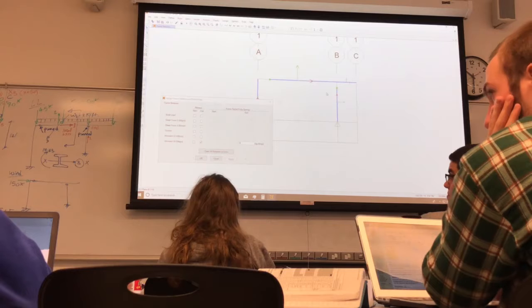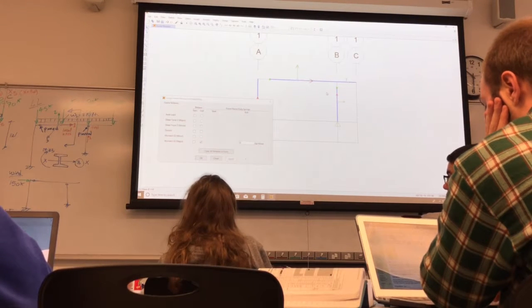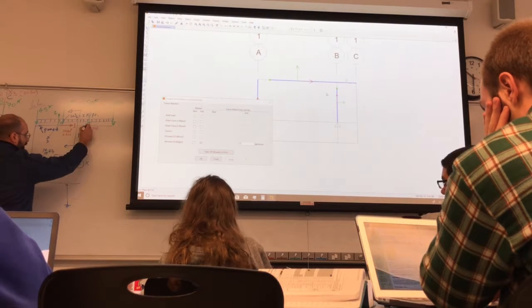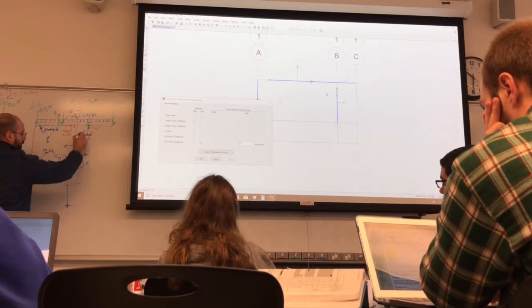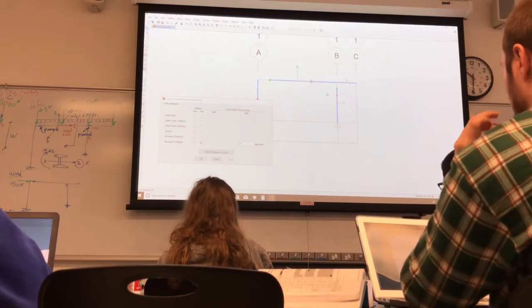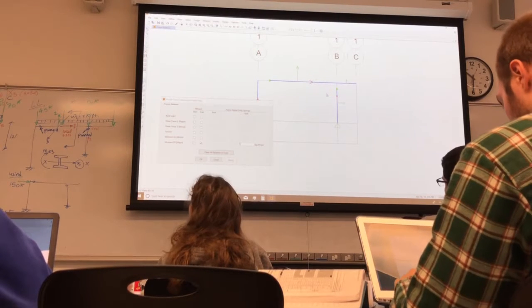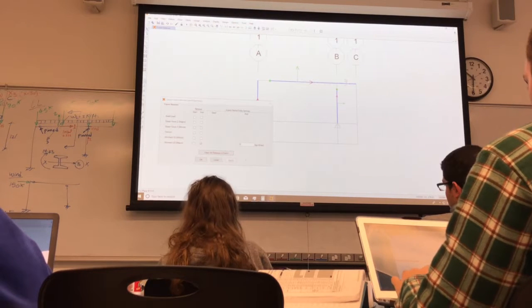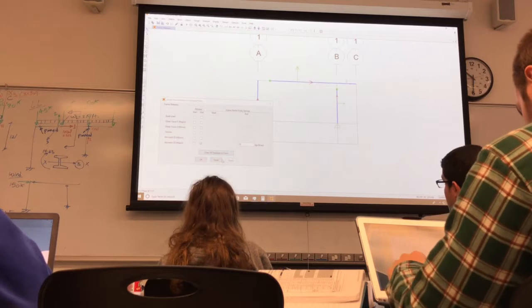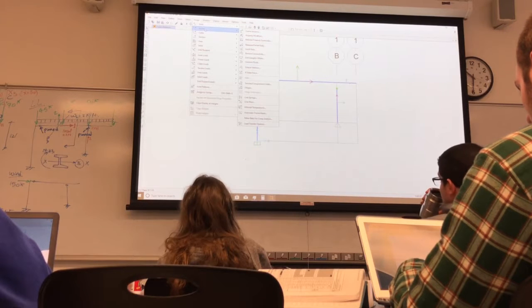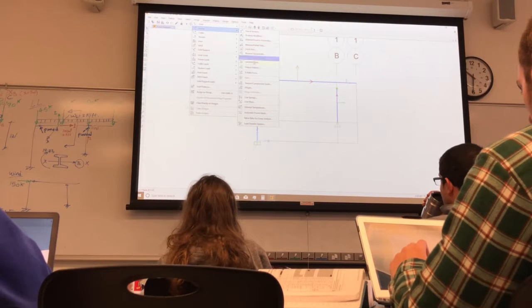So that's why you don't pin the beam. If I want to be too accurate, I should draw the pin like that. That's why some textbooks draw it like that, where it shows that the pin is in the column, because if it's in the beam, then it becomes unstable. You can't put it in the beam here, because the cantilever is going to fall, right? And you can't have a pin here. So we follow the same order. We did everything, we don't have anything else to worry about here.